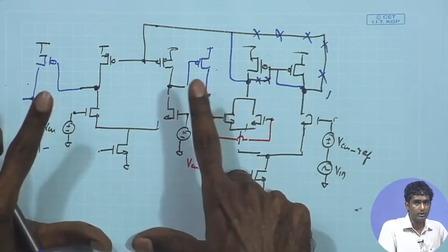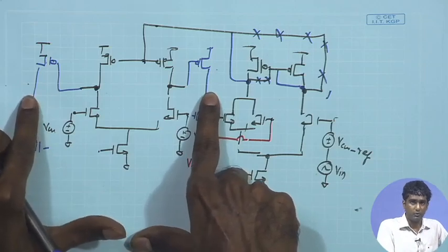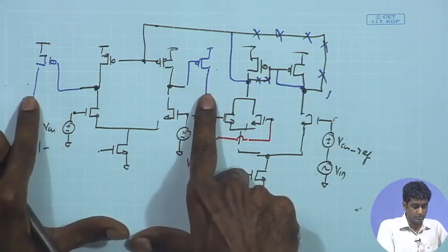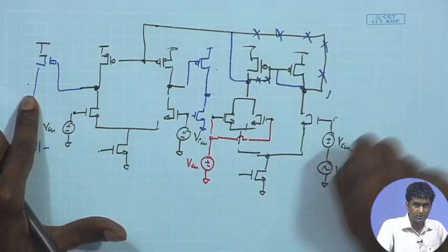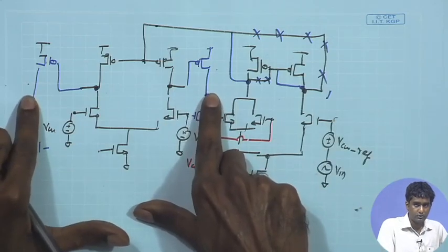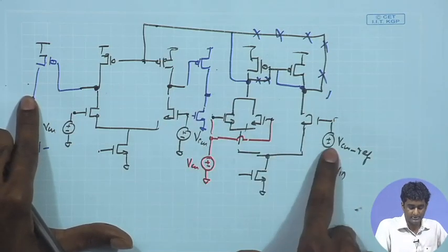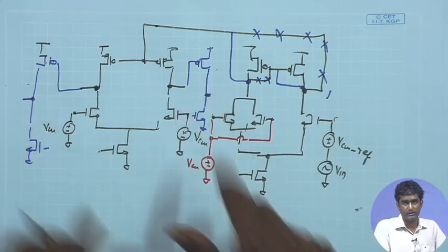Therefore, if you want to ensure that the output DC point is very close to the desired value in the closed loop, whatever DC you are applying at this point, for example, you can sweep it a little bit across the ideal value, and that will ensure that you are able to find the right precise value of the DC, so that this point is at the required value.